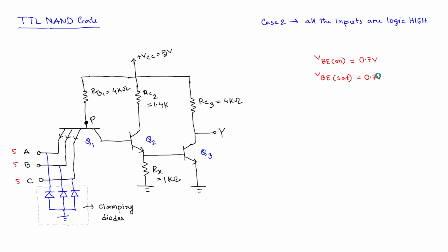So we just simplified our explanation such that whenever a transistor is in active mode or in saturation, in both of the cases the voltage from base to emitter required is 0.7. So now, to make it a little bit more accurate, we want to say the voltage for saturation, I mean base to emitter voltage, should be 0.8, slightly higher than that,